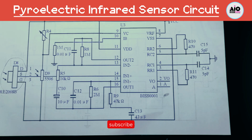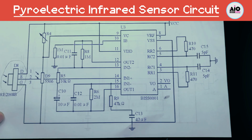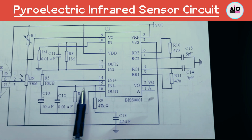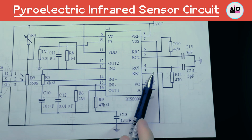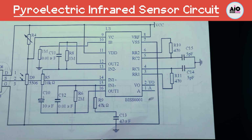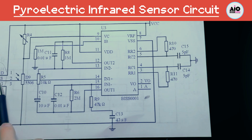There is already a front-stage amplification part in this sensor, that is to say, its induction signal has been amplified by the first stage and changed into a voltage output through the amplification of the field effect tube. However, its signal output is relatively weak and there will be some clutter entering, so it cannot directly control the load. The subsequent circuit further amplifies and filters the signal output by the infrared sensor, and then delay and other control circuits are added to achieve the purpose of driving the load.